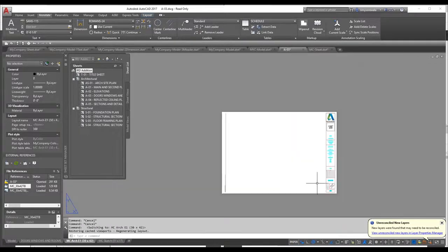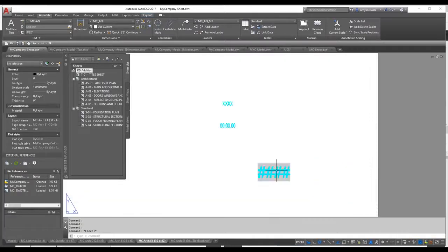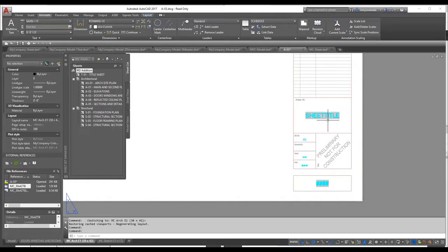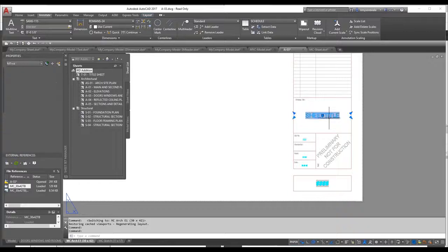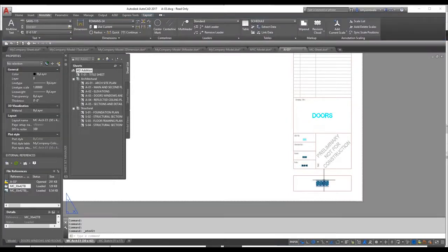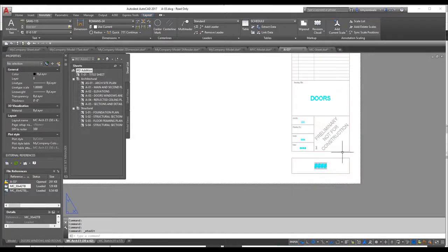The other thing about this XREFing is that the problem with XREF is you can't have attributes. So in my case, I have a separate block right here that is part of that sheet template that I did in the paper space. So when I create a new layout, the paper info comes in, this title block. So in this drawing, either it fills the information from the sheet set manager, or I can manually override it. So it allows me to quickly take care of that text information.